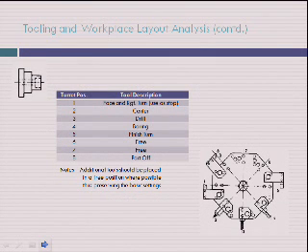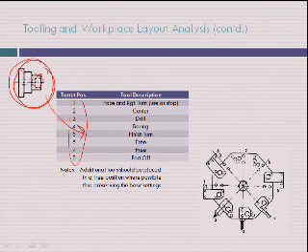Same concept of the composite component: what you have here is a single imaginary component, but it has the various features to be machined based on what the real parts in the family are. They look at the sequence in which the tools were used, and then they arrange the tooling appropriate to the sequence.